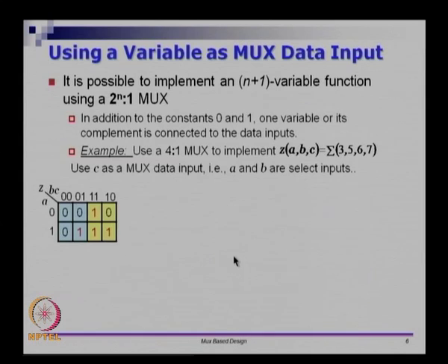This is the truth table, right. So we have the truth table with A on one side and BC on the other side, and you can see that minterm 3, minterm 5, minterm 6 and minterm 7 are all 1s, right. Once we have this, let us see how to get C out of this. So you look at combinations at a time. You look at these two cells here. In this case C is changing from 0 to 1, but the output is not changing, the output is remaining at 0. Even when C changes from 0 to 1, the output is 0, so you put a 0 there directly.